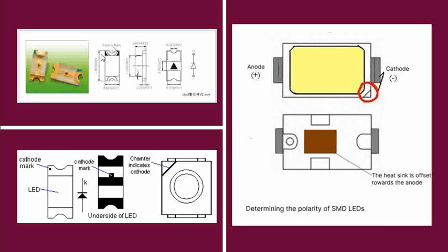In assembly, whether automated or manual, one of the most common mistakes is mounting a component in reverse, whatever the component. LEDs are mostly the biggest problem in such scenarios, especially if the marking is not understood by the assembly persons or if the designers haven't included it properly in the PCB.